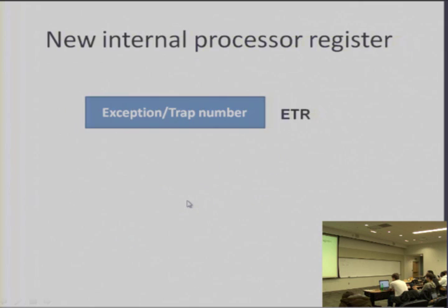First of all, when we have this discontinuity, it is going to result in the processor having to suspend what it is doing, and it needs to know what this discontinuity is. I said that I don't know where to go, and I need to. The processor has to find out where to go, and the way it finds that out is by having a special register in which we're going to capture the source of the discontinuity.